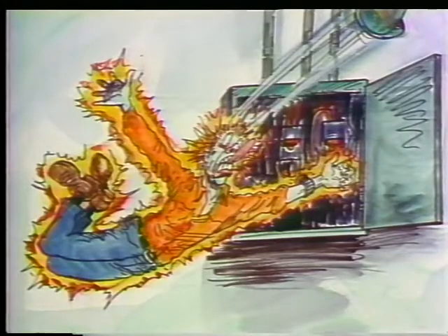First, we'll show you how to inspect a motor that's operating. Then we'll show you how to inspect a motor that's not running. By treating electricity with respect and with caution, you'll be able to work with it quite safely. But remember, it can be dangerous. So before inspecting a motor that's operating, take the necessary safety precautions. Remove any wristwatches, rings, or other accessories that might conduct electricity.